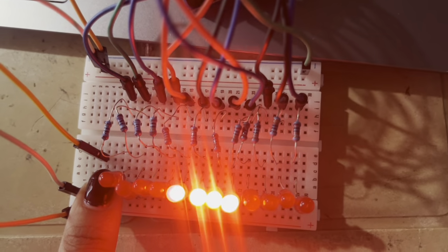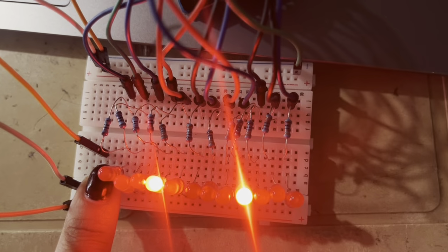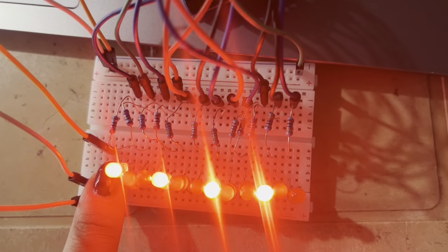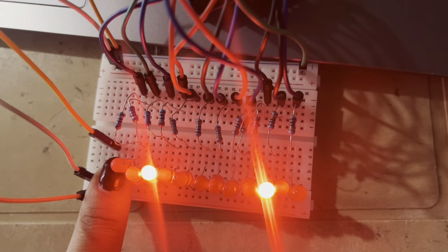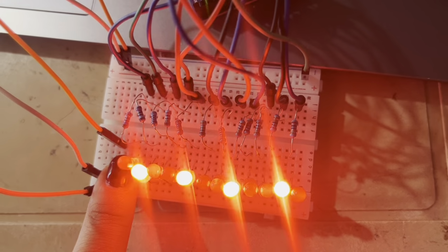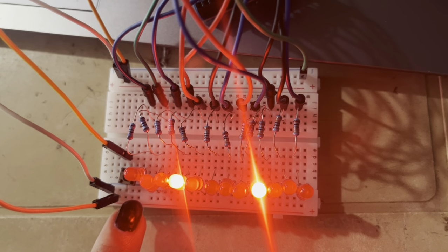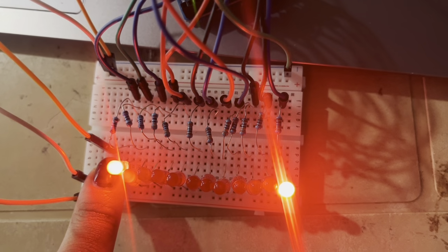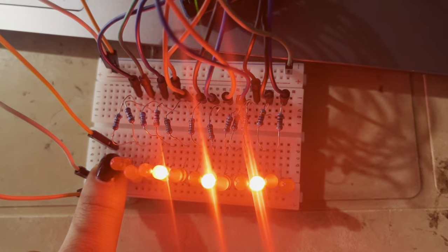As you can see, the tap switch serves as the main control element of the system. It is configured using the Arduino's internal pull-up resistor, allowing the program to detect a button press when the input reads low. While the tap switch is pressed, the LED sequence runs continuously. When the switch is released, the animation immediately pauses and the current LED configuration remains unchanged. Pressing the switch again resumes the sequence from the exact point where it stopped, rather than restarting the pattern.